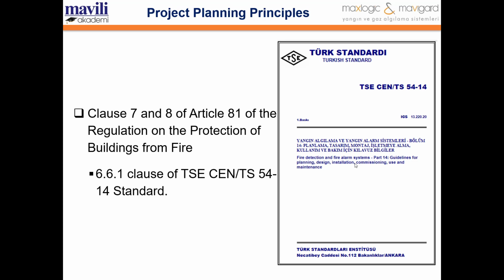In areas where audible alarms may be ineffective, for example, where background noise is excessive or where use of hearing protection is likely, visual and tactile alarm devices should be used to supplement audible alarms. In areas likely to be used only by the hearing impaired, procedures should be in place to inform them of the alarm, and visual or tactile alarm devices should be used to supplement audible alarms.